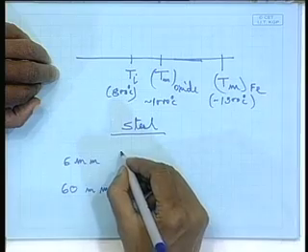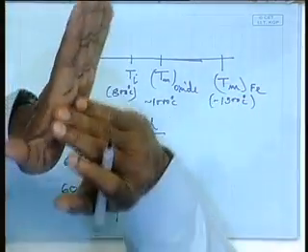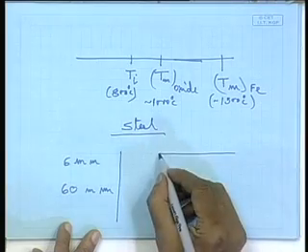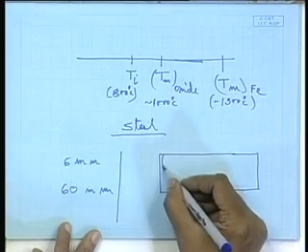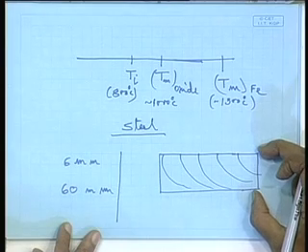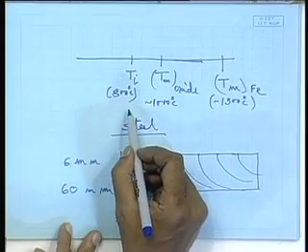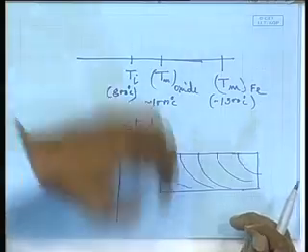Now, here what happens, like in mechanical cutting we had, yeah, all those things will come. Immediate effect would be the quality of the cut edge. In case of mechanical cutting, we had a very good quality of cut edge. In gas cutting, oxyacetylene cutting, your quality of cut edge will depend much on the speed of cutting. If you have to cut at a slower speed, your edge becomes more rough. That means, if you look at the cut edge, it will have some such marking, right. By this I wanted to show thicker plate, you need slower speed of cutting, because you have to attain that temperature level. So, you will have to give more time for the heat to flow, right.